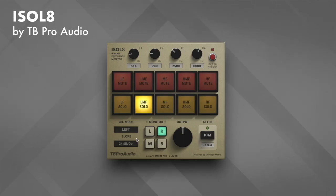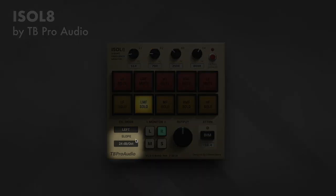And then right below, we have the slope of the filters for our 5-band frequency monitor. So if we want these crossover points to be a little bit steeper, we can go ahead and click it and do 48 decibels per octave. Let's hear the difference between 48 decibels per octave and 24.